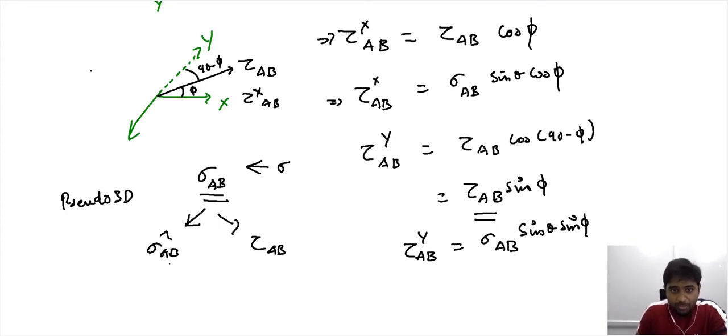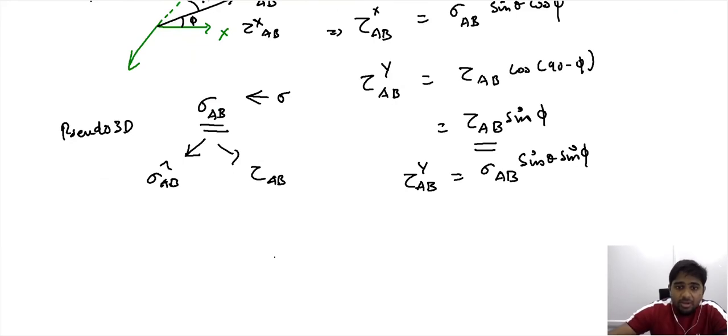The normal component acts in the normal direction, and the shear component acts along the plane of the region of interest. Now when we look closely at the setup we have considered, we realize that the description of the shear stress is rather restricted, because AB is not a line, it is a plane.